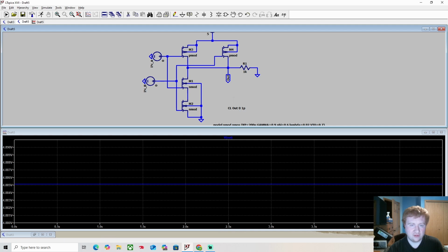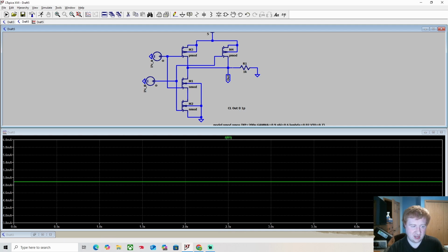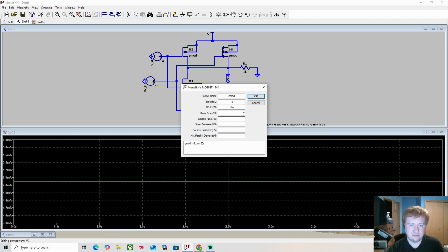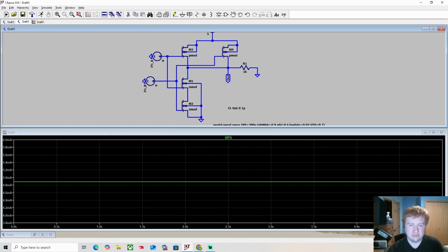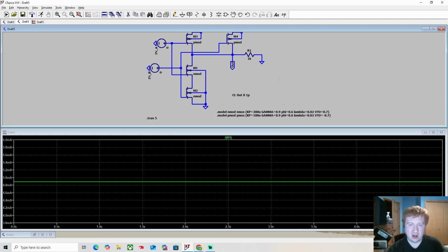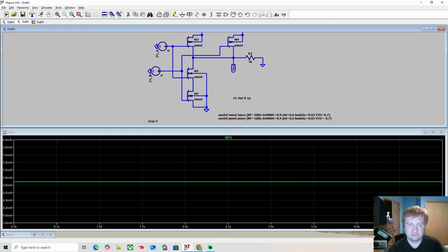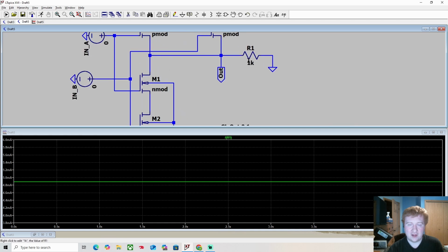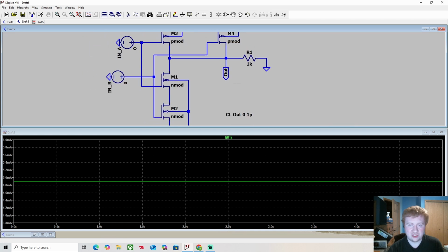But there is current flowing, and now that we see that, all these different parameters are probably why it's a low current if I were to use the full 5 volts or 1 amp. Usually these logic gates aren't supposed to supply a ton of current. At most, up to 10, 20 milliamps maybe, depending on the system.